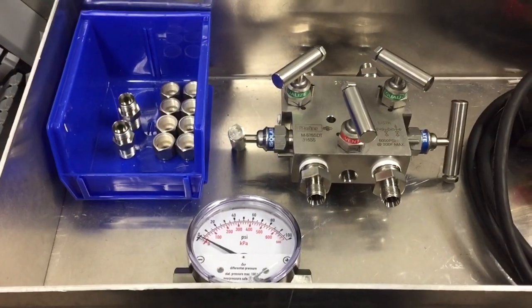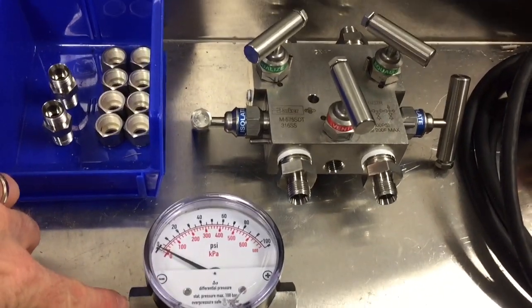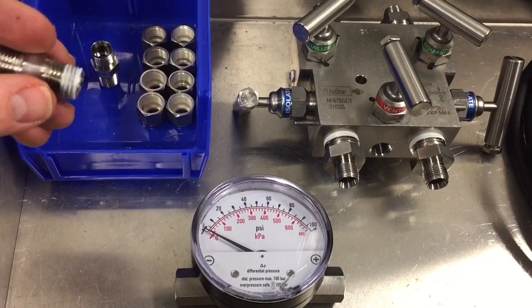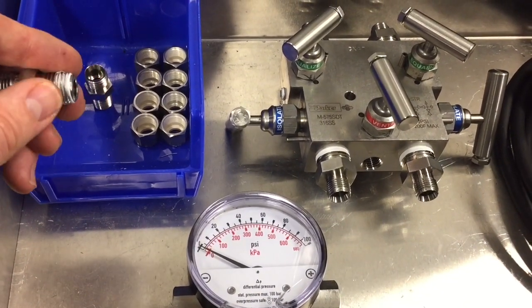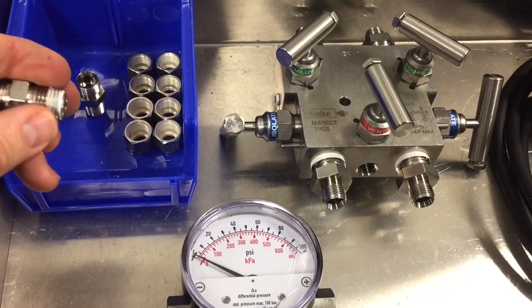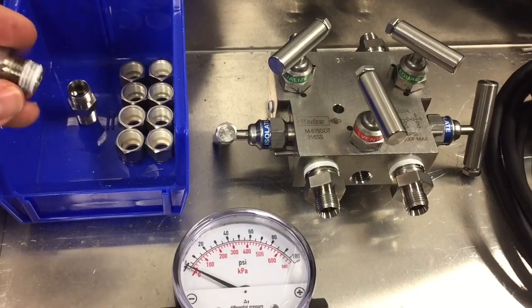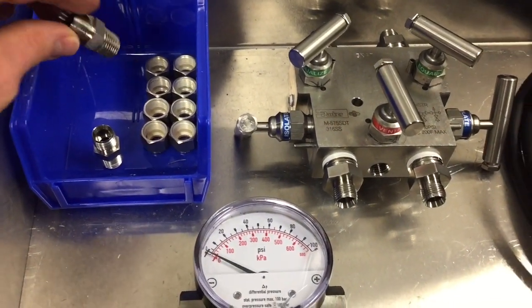Right, so after disassembling all the equipment, we should have the differential pressure gauge with the tubing fittings removed. You can see I have them sitting right here. Most of the Teflon should just peel off. I do see I still have some left here. If you can't get it all off, you can take a wire brush to it and clean that up so all the Teflon tape is off. This one here, all the tape came off, you can see.